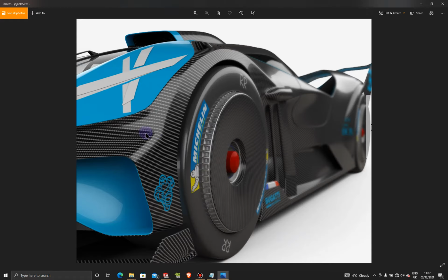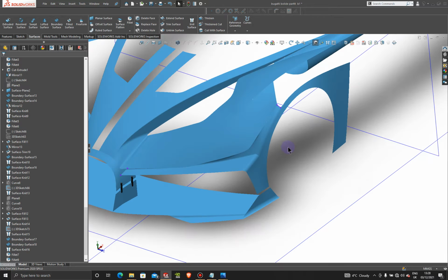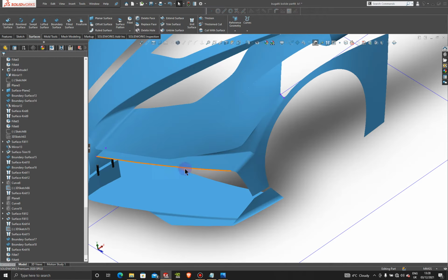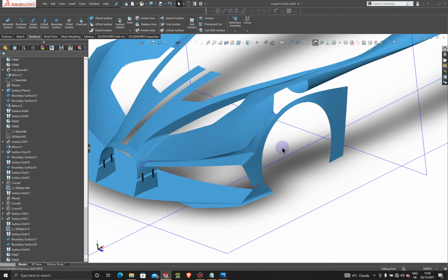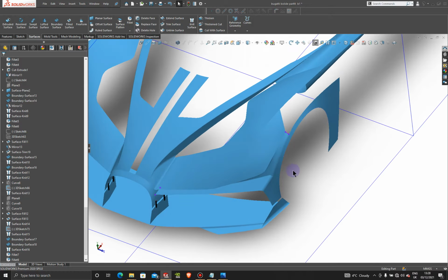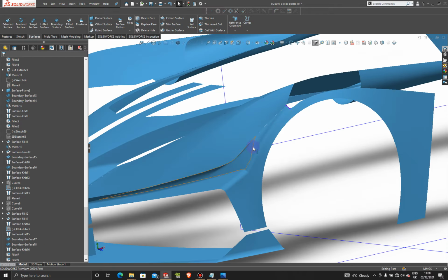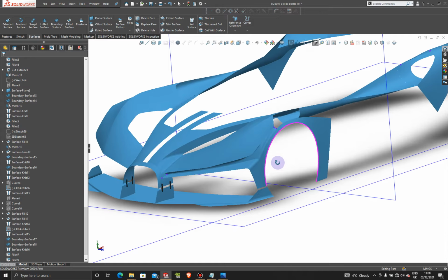So we're gonna go to fillets again, and we're gonna try just a normal fillet. And probably 6 is not possible, so 1 or 2. So let's just do 1, and I think 1 is perfect. It gives a nice edge on that. Perfect. All right, so that looks good. And then we're not going to connect this to the body yet because we still have to mirror it over, right?